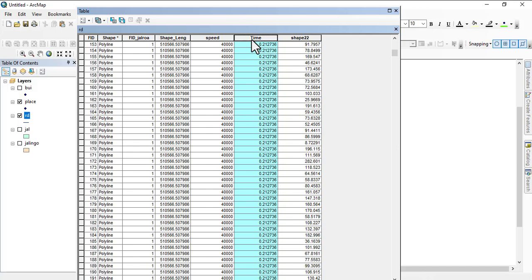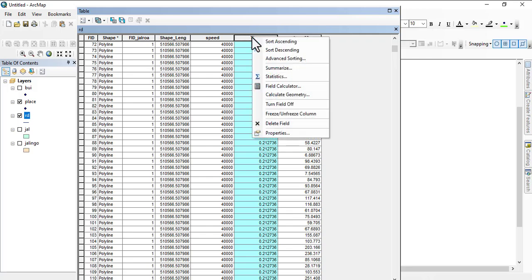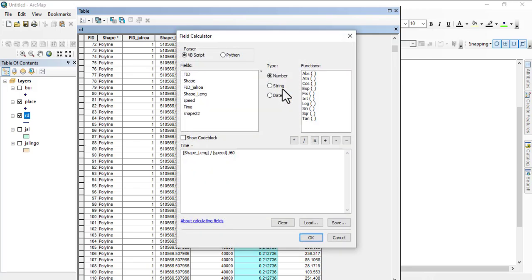Right click, then field geometry. Calculate geometry. So that's length. So click on calculate. So you see now the length. You see the other one. The length are showing the same thing all through. Now this is now the length of our roads. So we'll now go back to calculate this. So go back to field calculator, time now. So it's shape.